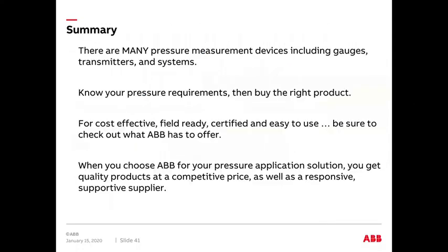So in summary, I went through a lot of different things very quickly here, but there are many pressure transmitters out there, and there are systems in all these industries that need those pressure transmitters. Like choosing an automobile or a computer, you first need to know what your requirements are, and then you need to go out and look at what products are available and buy the right product. You don't want to buy a product that's going to measure 1,500 PSI or 15,000 PSI if you want to measure a tank level, which is going to be more like 6 or 8 PSI.